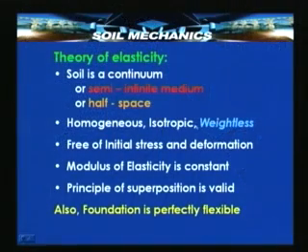Coming back, in addition to these assumptions, we shall also be assuming that the medium is free of all initial stresses and deformation. Actually, this follows from the simple assumption of weightlessness, because if there is no weight, there is no initial stress and no initial deformation. We have already defined the word isotropic. From this it follows that the modulus of elasticity and other parameters such as Poisson's ratio or the shear modulus, which define the elastic nature of the soil, are all constant with direction. And then finally, we will assume that the principle of superposition is valid.